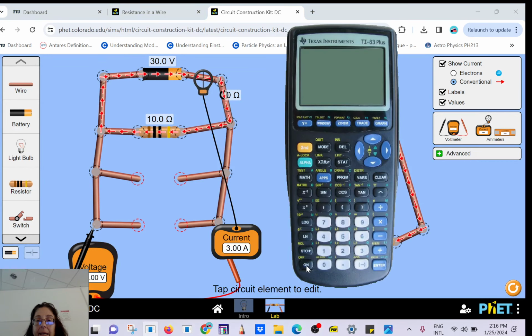Okay, so you take, what was the first one here? Was 20, do you remember? So we have 20, 10, and 10. So you do the following. It's the recipe. You take 20, and then you take the reciprocal, so to the minus 1. Do you all have that function with your calculator? Otherwise, you do 1 over 20. It's the same thing. Plus, okay. And then you do 10, and you also take the reciprocal, so plus 1 over 10. Okay. Plus, and you do that with all the loads.